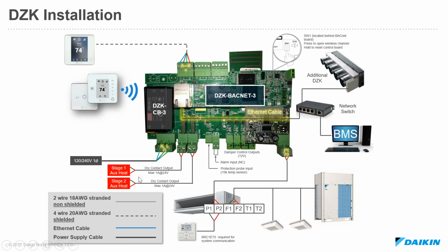We have the stage 1 and stage 2 auxiliary heat contacts. The DZK does require 120 or 240 volt single phase power. So you'll see that power landing point on the DZK's main board.